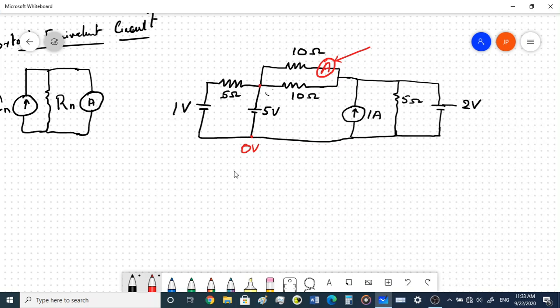The potential at this point would be, you have a 5 volt source over here, which makes the potential over here 5 volts. Now at this point the potential would be, this is 0 because it's connected to here, this would be 1 volt. Now let's take the potential over here, this is 0, this is 2 volts, so the entire node is 2 volts, right?